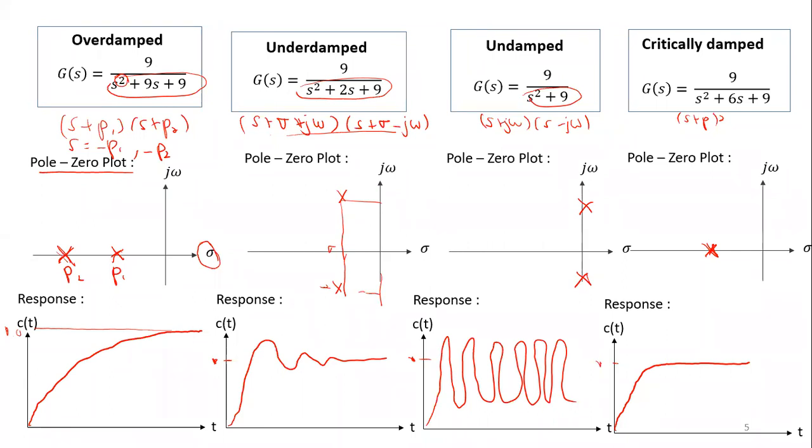Sometimes we need the antenna dish to move fast, right? So we usually need an underdamped response where it will move fast, but the problem with underdamped response is it will have some overshoot. It moves fast, but the setback is it will move above 90 degree, for example like 110 degree, and it will swing sometimes before it reaches 90 degree.